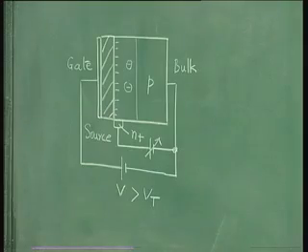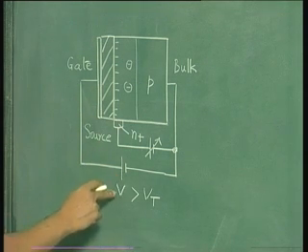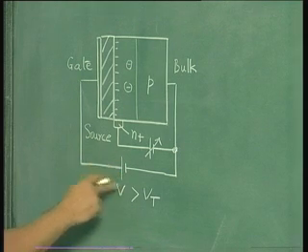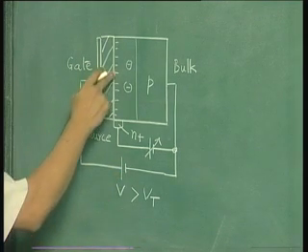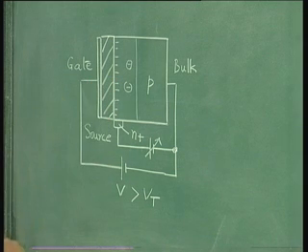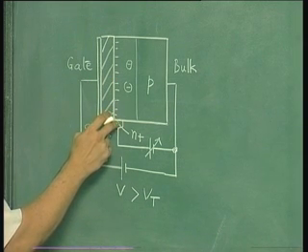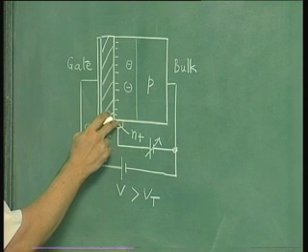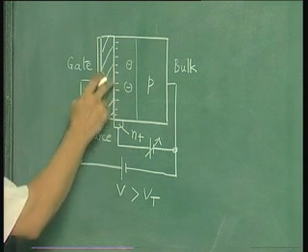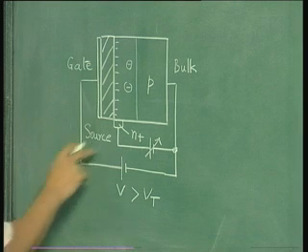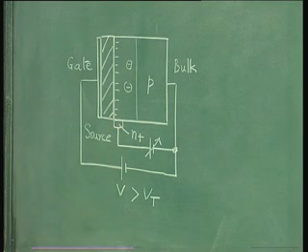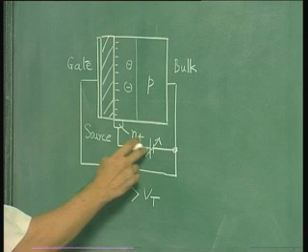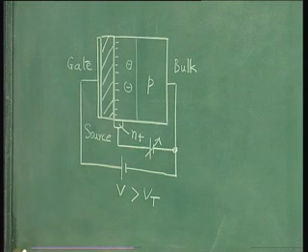So unlike that situation, in a 3-terminal MOS capacitor, once you provide the N plus contact, even if you make changes in the gate voltage at very high frequencies, you can have this inversion layer responding to the change because this N plus region has a large supply of electrons and it can provide electrons as fast as this layer needs. That is why this contact is referred to as the source, because it can source the electrons required for inversion layer changes.